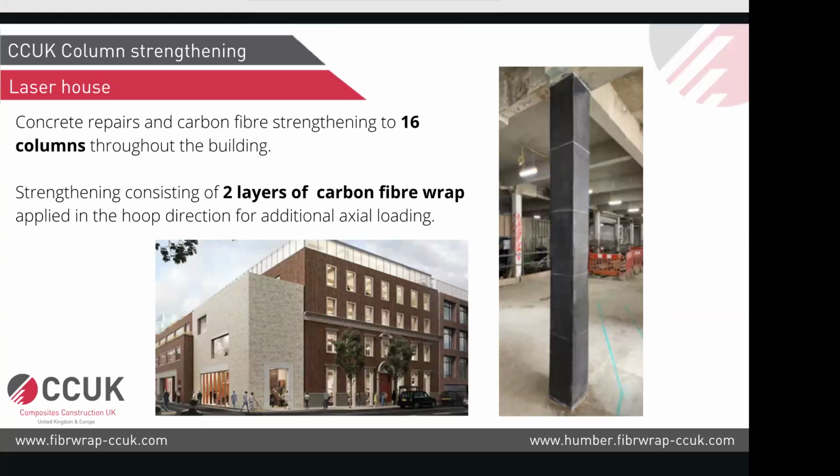So when we looked into this project along with the engineer, we found that there is some longitudinal rebar and links available in this encasement. Now, according to Eurocode, there is a clause that if you have the minimum longitudinal rebar and links present in an encasement, then you can account for that encasement as contributing axial load bearing capacity, as in the case of a composite column. So when that was done, the columns needing strengthening went down from 80 to 20, and those 20 columns needed strengthening purely because the strength of this concrete encasement was just less than 20 MPa, which is the minimum requirement.